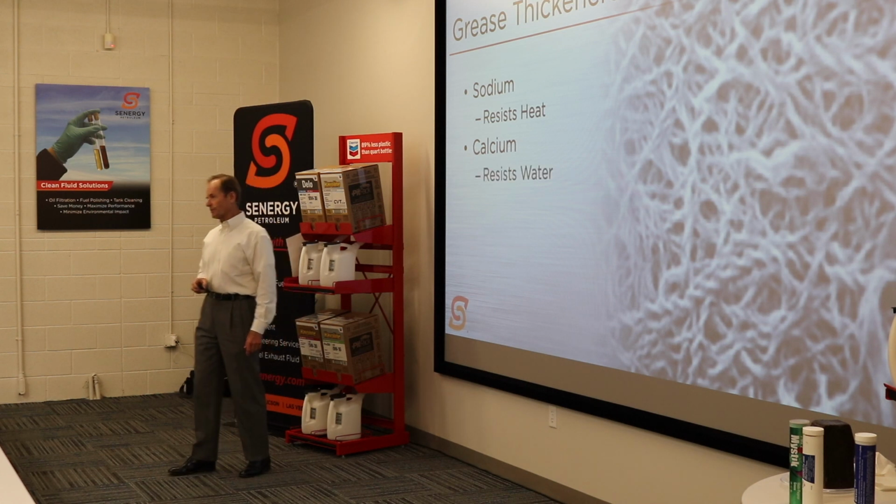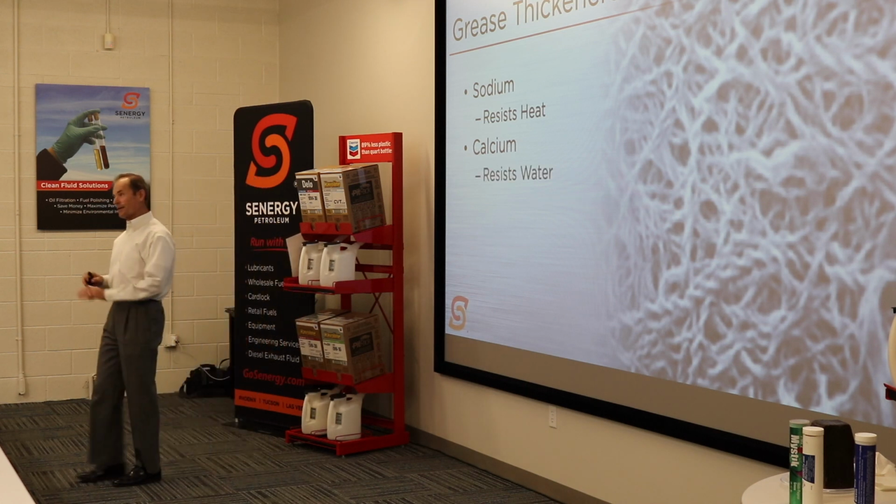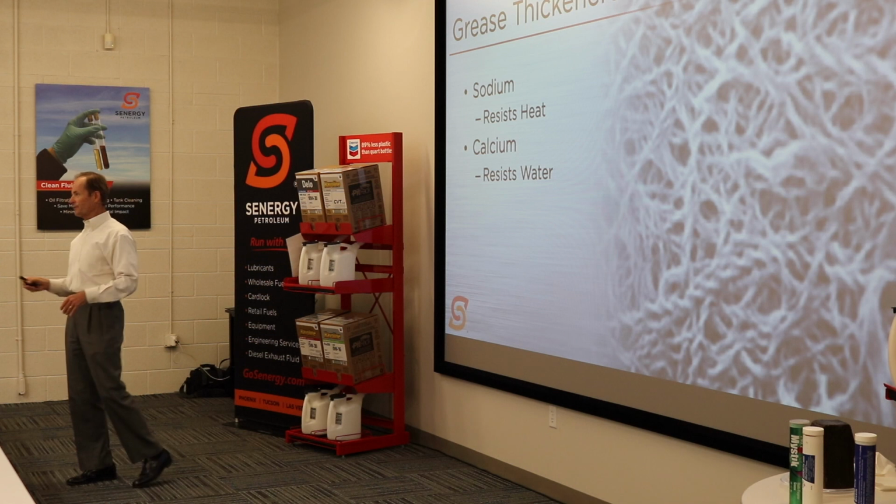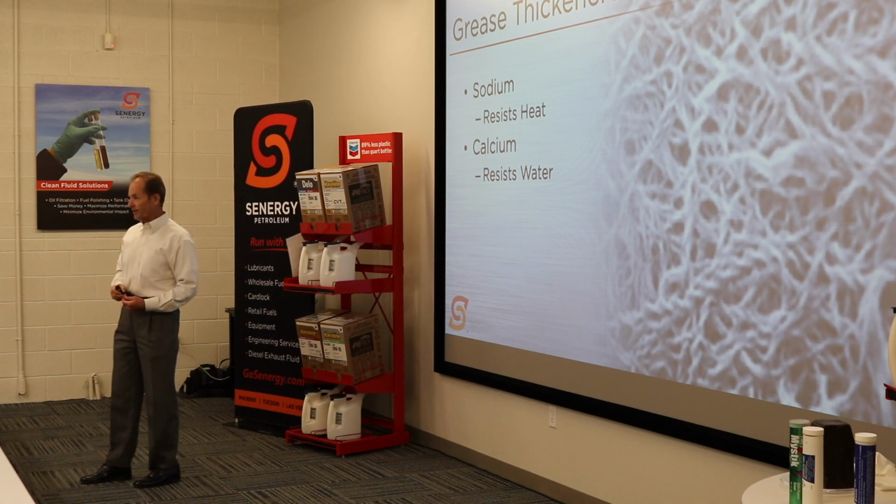So he'd get out his chassis grease. His chassis grease is a calcium-based grease. Okay? Calcium-based greases are very good at resisting water. They're not all that good at heat, though. You don't want that on your wheel bearings.